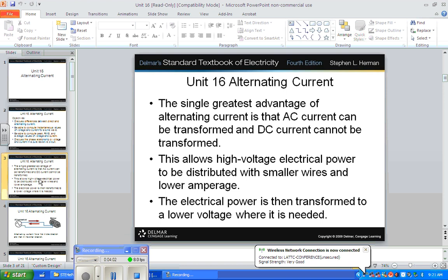So what they do is they kick the voltage way up to, say, 1,000,000 volts. So now the same amount of power, a gigawatt, let's say, divided by a very high voltage is a much lower current, right? And we might get here with some voltage left. We won't lose a large part of it to the voltage drop, the heat loss of the wire.